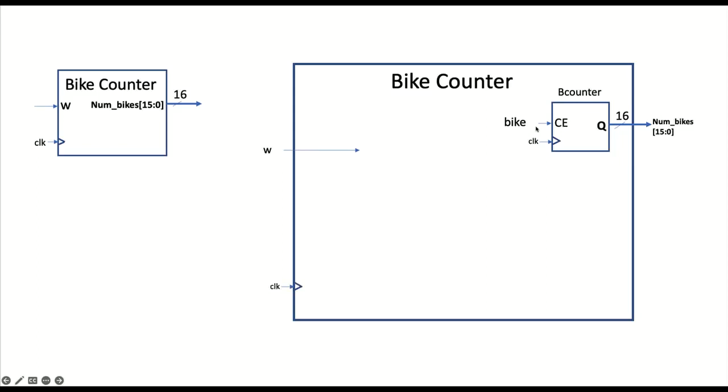So in order to detect that pattern, what would I need to do? Do I need another counter? No? Yes, I think I'm going to need a state machine, but this is going to be an awfully big state machine if I have to have a state for each one of those clock cycles in between the two wheels.